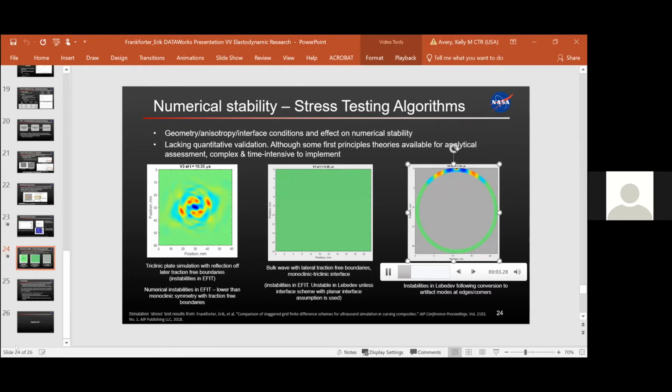This is actually not a verification, because we would have had to use something like a method of manufactured solutions, for analytically creating a solution and testing that the derivatives are solved suitably. This is a bit of a step below verification. This is just a stress test, but we find that even when it's very difficult to have an analytical solution, just employing one of these is pretty quick to do, and can provide a means to completely veer off of an unsuitable simulation algorithm approach.